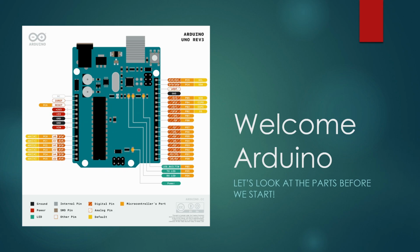And this is the feature of a hardware development platform. You have a lot of auxiliary stuff that is built in, let's say 10%, and you have the other 90% free for your own usage. So if you want to connect something to the ATmega328P, you connect it through these pin headers. For example, you can connect an analog signal to this pin here. This pin is basically the pin called PC0 on the ATmega itself.